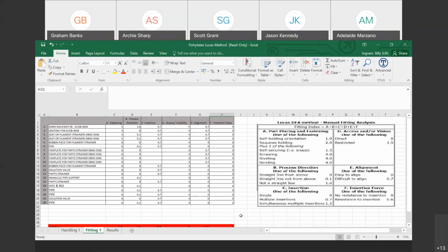And also, I think for the alignment, difficult to align, it's quite restrictive. That's an estimation, but again, I assume there is nothing easy to align. Yeah, but again, we treated that as, the alignment one is pretty obvious to see which way it goes, if you know what I mean. The pipe's got a certain shape, and if you're looking at your drawing, then you should be able to see that. But the difficulty will come in where the pipe's built in a shop to one tolerance, and the ship structure is built to another tolerance. Yeah, so whether that matches or not, there might be some rework required.